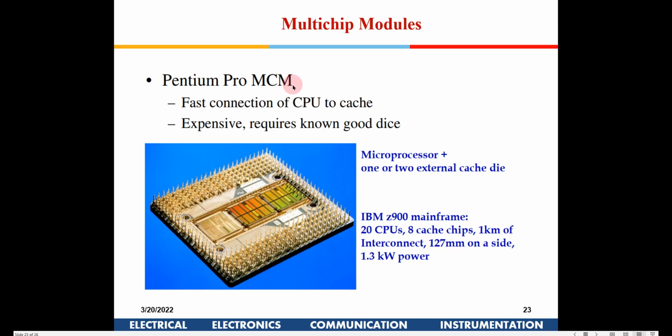Now this is again a Pentium Pro MCM processor. This chip, if you see, is the microprocessor, and these are all the pins available here. You could have an external cache memory also, placed close to the chip here, right? We know why a cache memory is used, right? Some portion of the program from the RAM, which is very often used, is brought into the cache memory. These are generally SRAMs; they are not dynamic RAMs. So some portion of the program which is constantly being referred to will be brought into the cache memory, so that it speeds up the overall speed of the operation, right?